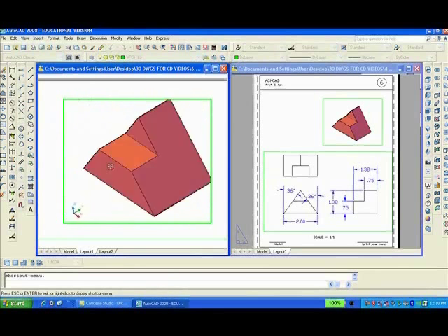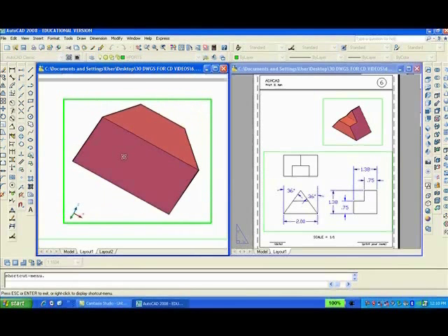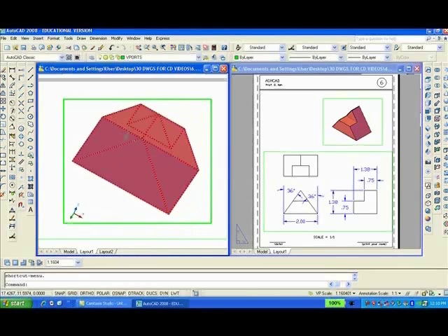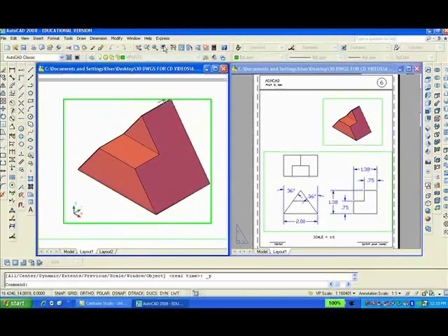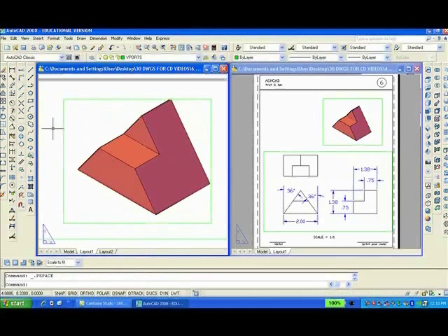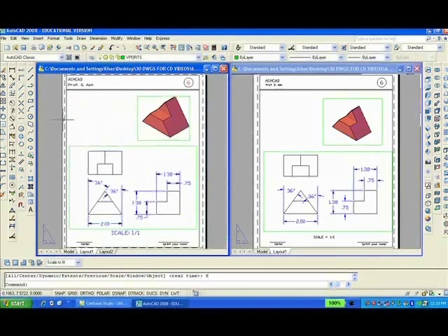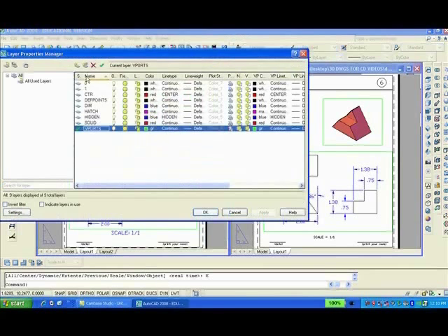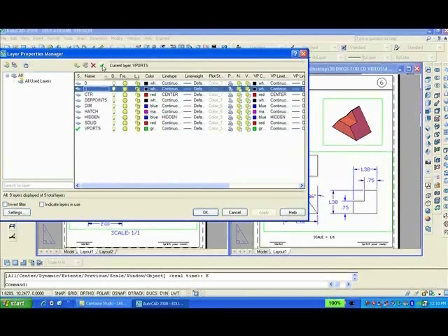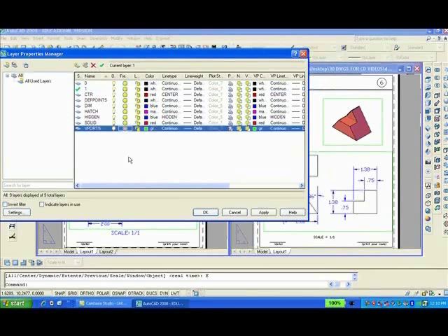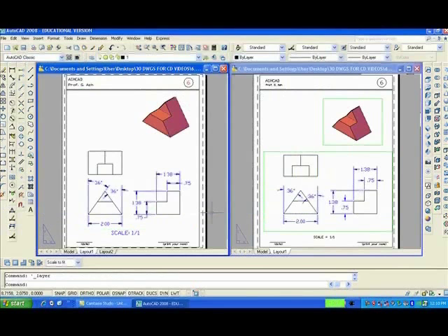I went kind of fast, but that's alright. I'll stop it. It looks okay. I'll exit and zoom previous. Double click outside to get back into paper space. Z, enter, E, enter. Everything about this job looks okay now. So I'll go to layer, make layer 1 current, freeze layer viewports to hide the two windows, the green windows.